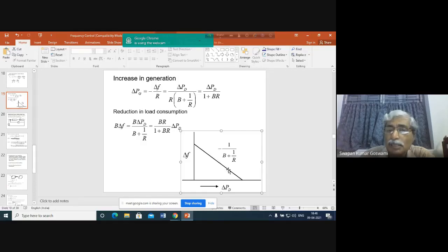This frequency is being restored, and this frequency is restored at this load. Means what is actually happening, if we draw a perpendicular line from here, and also a line for frequency error, then somewhere here is the operating point. An operating point obviously should lie on the system load frequency characteristics. It cannot be outside that. That means that these operating characteristics, as if it had been shifted from here to here, have been shifted parallelly, because slope cannot change.